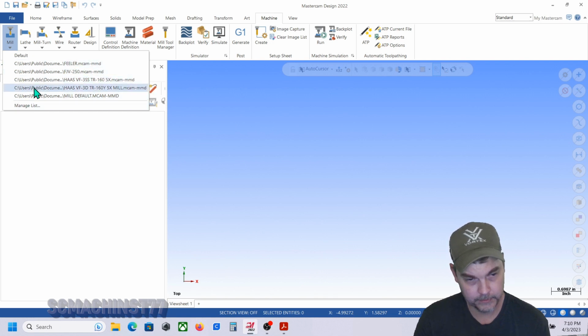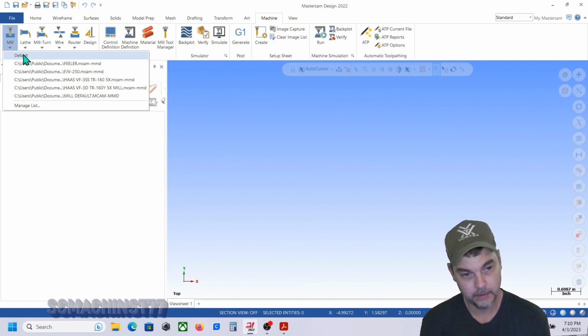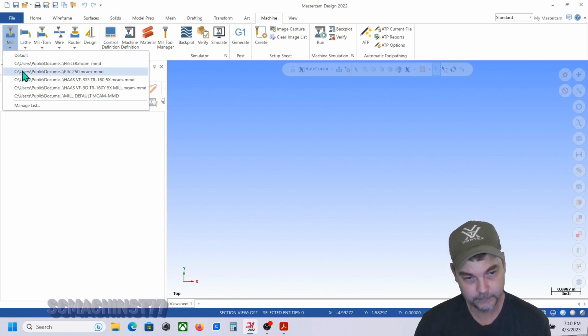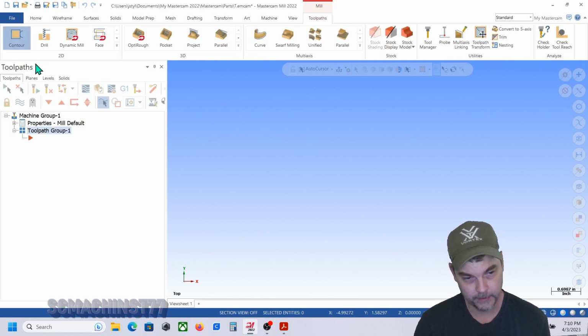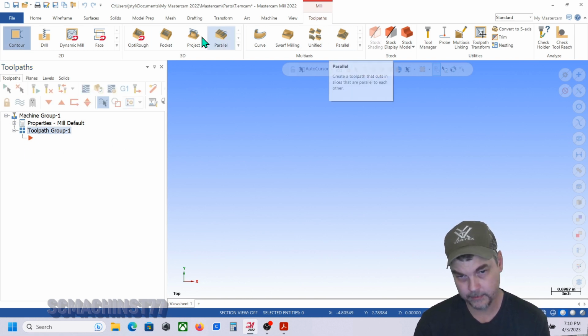Yours is going to look different than mine. It'll either not have anything in it, or it'll just say default, especially if you've just downloaded Home Learning Edition and are following along in it. You should just be able to hit default, and then it's going to bring up just a default mill, which should be good enough for this. So once you've got that opened, it automatically goes straight to your Toolpaths menu or Toolpaths tab.